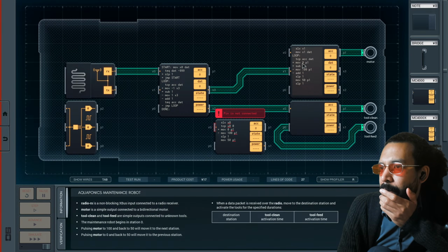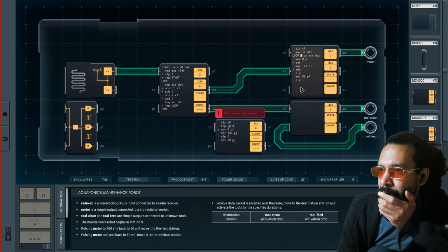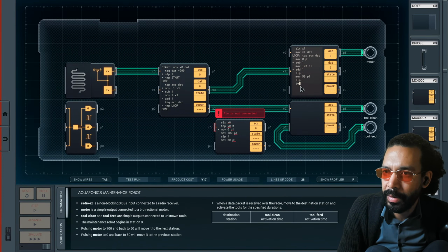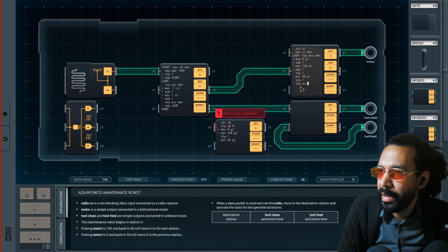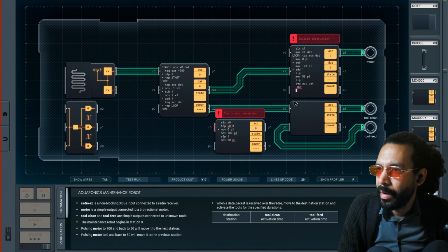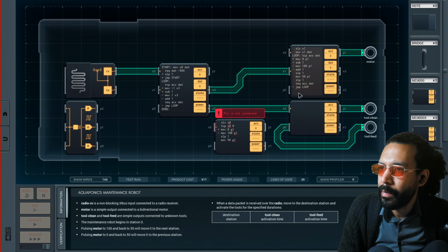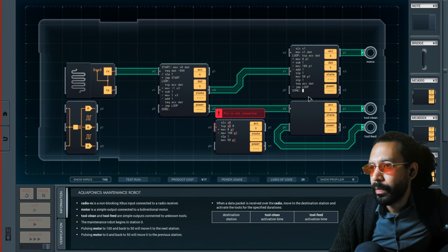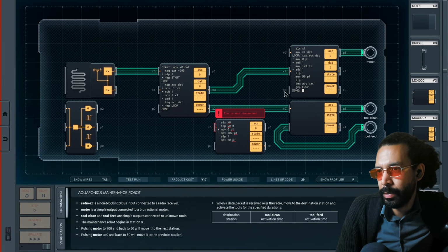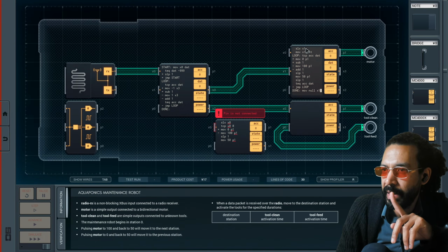Okay. And then after all that, well, we have to do our test. So test equal accumulator and data. And when they are not equal, we jump back to the loop. It's still the same code we had from earlier. Otherwise, we execute our done code, which is going to be to send the signal back on x1. So move null to x1. And then we go back to waiting.